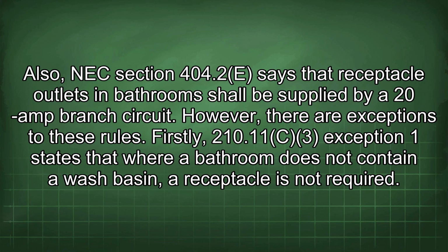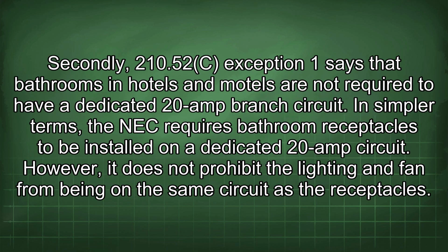However, there are exceptions to these rules. Firstly, 210.11(C)(3) Exception 1 states that where a bathroom does not contain a wash basin, a receptacle is not required. Secondly, 210.52(C) Exception 1 says that bathrooms in hotels and motels are not required to have a dedicated 20-amp branch circuit.